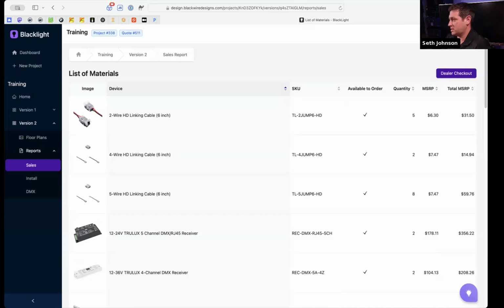Oh, there is a question. Can you explain the 96? Yeah. Class 2 is an electrical rating on the power supply that's in the electrical code. And if you go over the class 2, if you go over that 96 watts, you're going to need to pull a permit. It's considered more of like a high voltage thing. So there are jurisdictions and there are inspectors that will dig through your equipment and find the non-class 2 power supply and ding you with it.